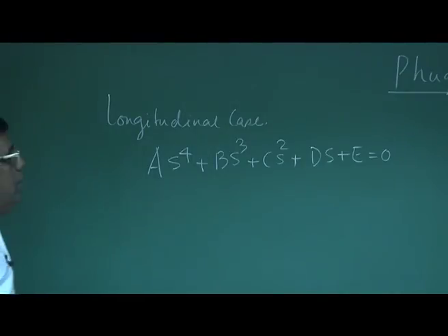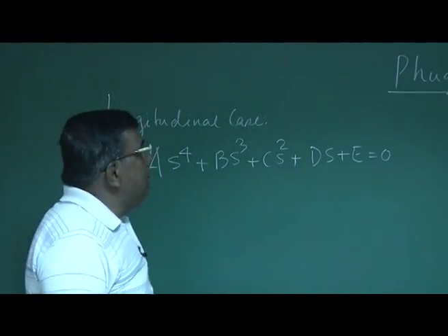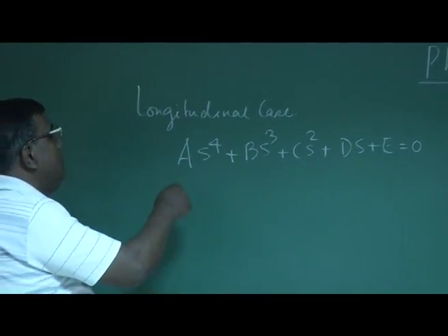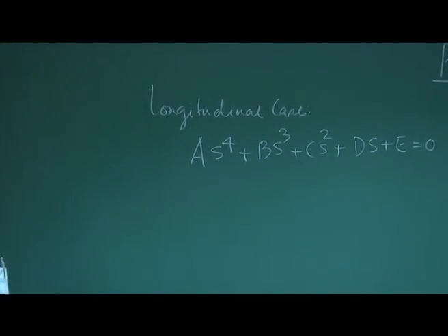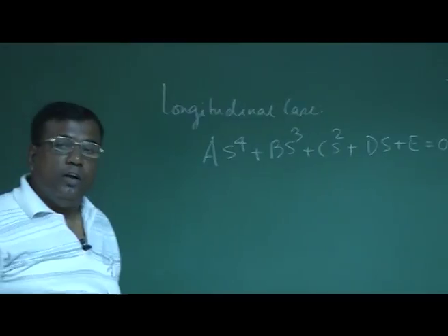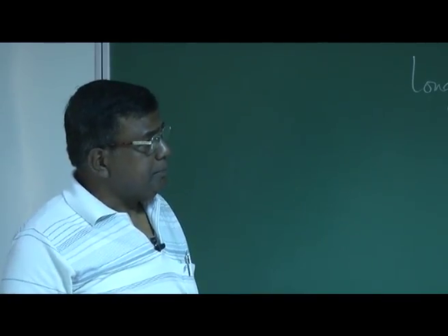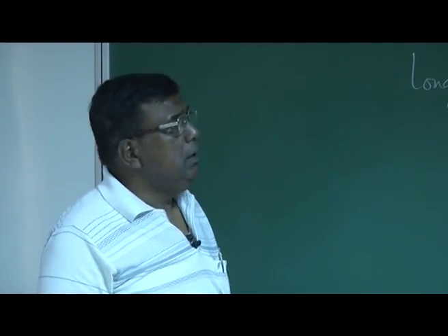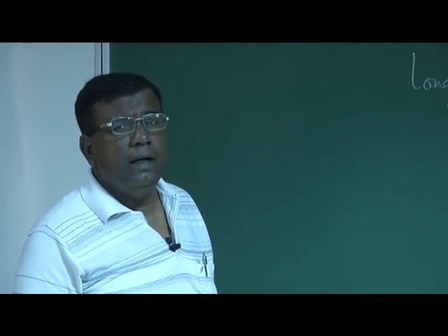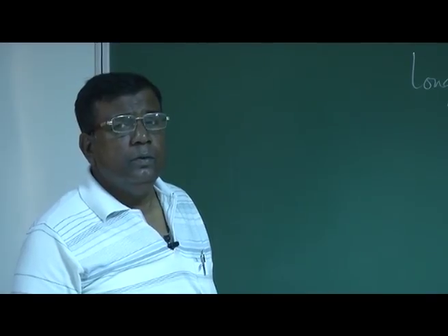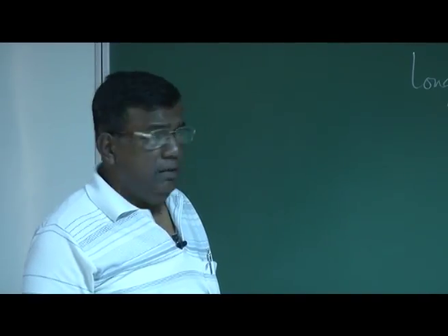And what we found from a numerical example was that once we find the roots, we get two complex conjugate pairs. One we attributed to the short period mode, that is, when disturbed, it comes back to equilibrium in a very short time, and during that time it is fair enough to assume the u perturbation is 0, speed remaining constant.